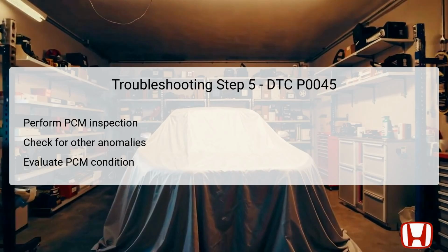Evaluating the PCM condition involves checking module inputs and outputs for consistent operation during the testing procedure. If the PCM is found to be defective after ruling out all other components, replacing it may be necessary to rectify the issues related to DTC P0045. Proper diagnostics at this stage ensure that the source of error is accurately identified and resolved.